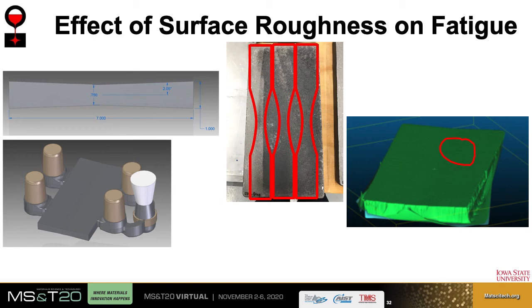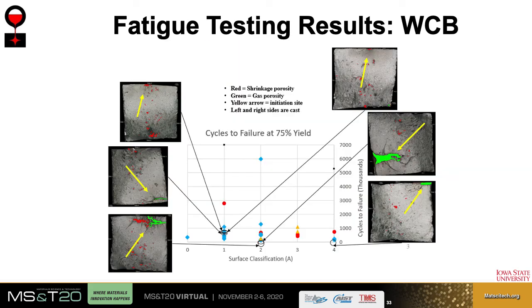It was hypothesized that the surface roughness of castings does not control its fatigue performance because it is not the largest feature. We cast plates with different levels of surface roughness based on strata surface comparator plates. The plates were designed so we could extract tensile specimens with at least two as-cast surfaces. So these cast plates were made with much more severe indications than are actually in production steel castings.